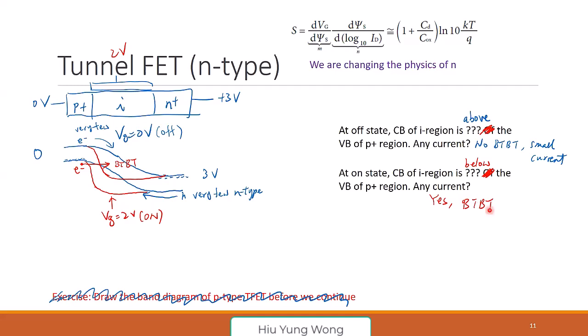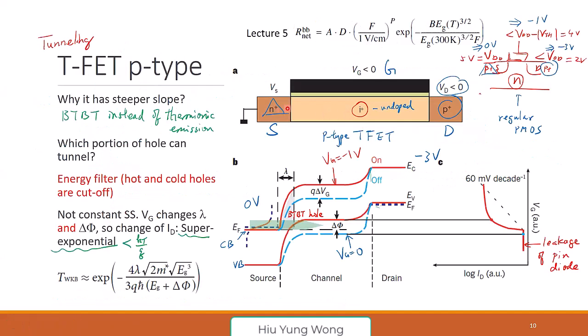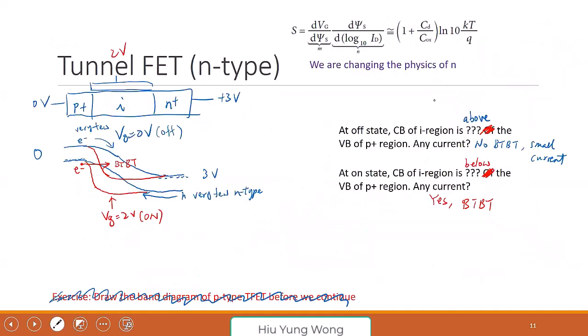Okay, so now go back to your original question, right? Just now at the beginning, someone said, this is not a transistor. How come P and N? You have a PN diode, right? This is N type, PIN. This is P type, NIP. Just remember they're just PIN, NIP. For PMOS, drain is at P. For NMOS, drain is at N.